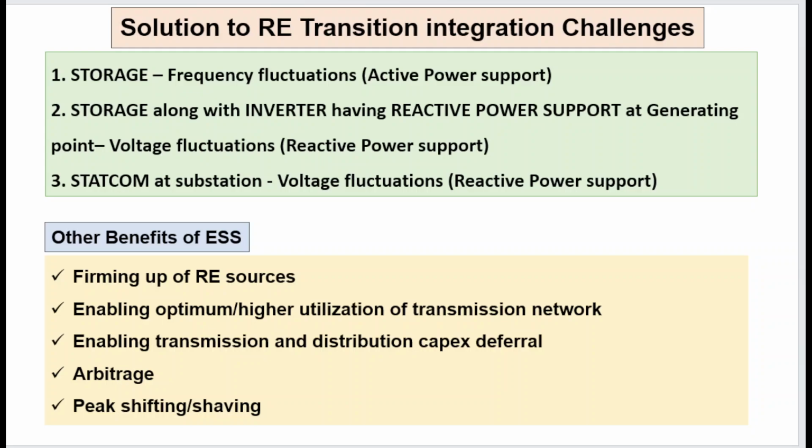Now in our country, we basically have pumped storage projects and battery energy storage systems. In batteries also, we have mostly lithium-ion battery storage systems at present, and sodium-ion is also under research at various IITs, but it is not commercially deployable at present. There are other benefits of energy storage systems in addition to the above, like supporting frequency and voltage.